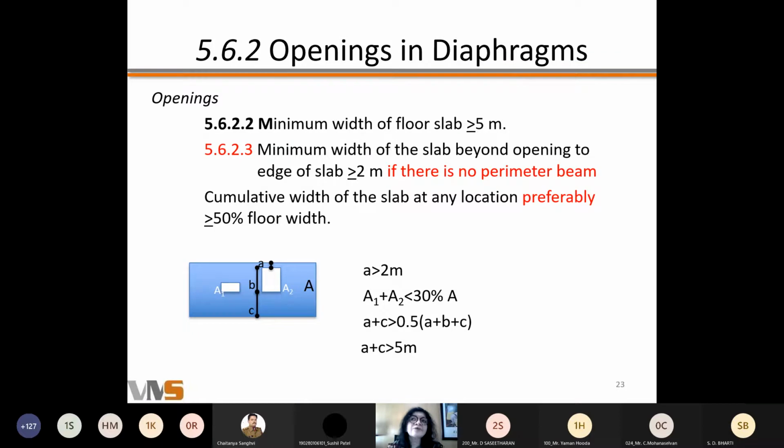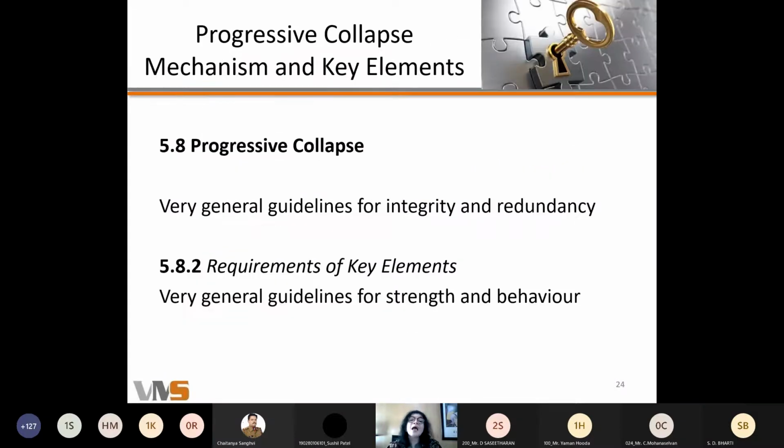As I said, drift control and lateral loads drive the design of tall buildings. And so you need to have a very clean, well-defined path for your lateral loads. The diaphragm is the path, and so giving sudden cutouts will confuse the whole load path system. And so you need to be careful about that.